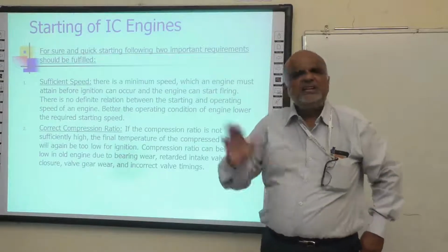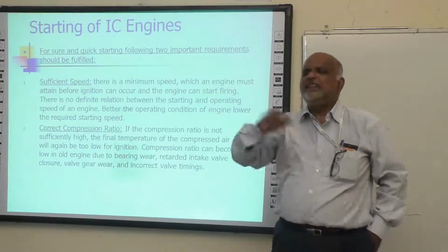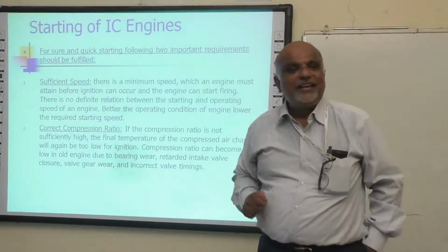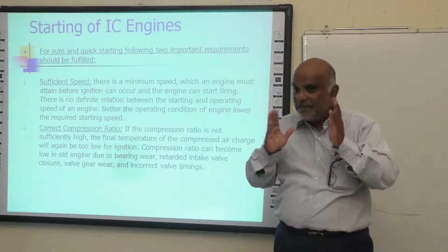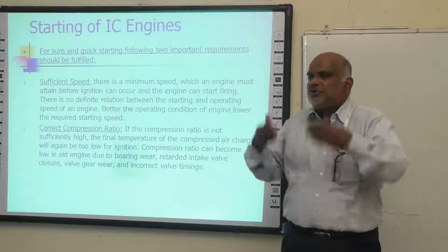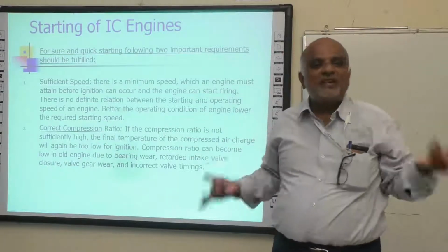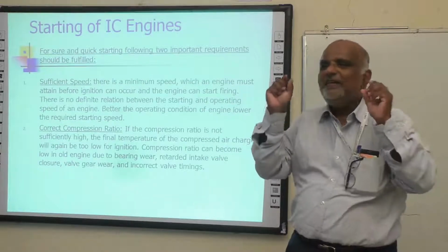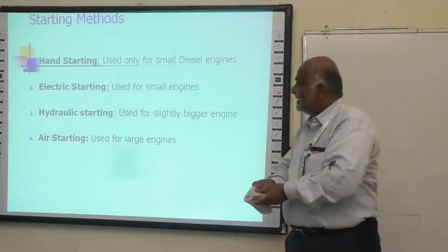Now, that is not the same in all ships and all engines. It depends upon how well you maintain it. If you renew the bearings in the period given, then of course it's going to reach its original compression ratio. Then you can start the engine in the right time with a very minimum RPM. Next slide.